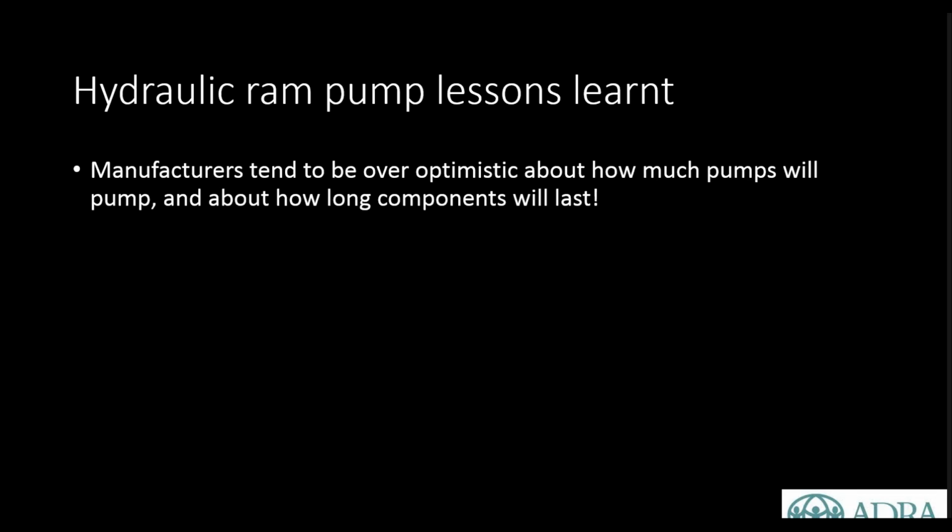So some lessons learnt. From our experience in Vanuatu, manufacturers tend to be over-optimistic about how much the pumps will pump, and also about how long components will last. In just about every renewable energy pump system that we've put in place, the pumps actually delivered a bit less than what the manufacturers said they would pump.